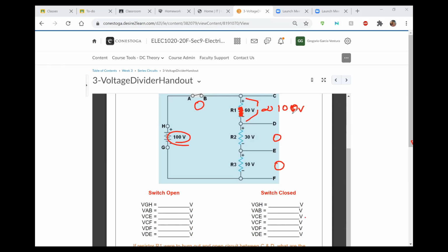If you ever go to a wall switch and you measure and you don't get full voltage, your 120 volts between the neutral and one of the terminals of your wall switch, immediately you know that the breaker has to be off or that the wire was cut somewhere along the line, because you should always have 120 volts between the neutral and your switch.